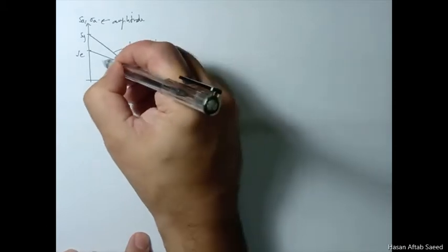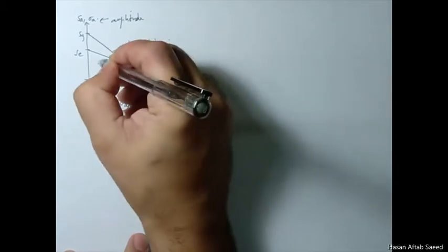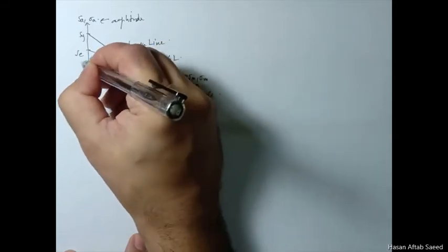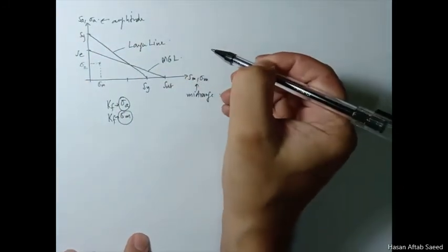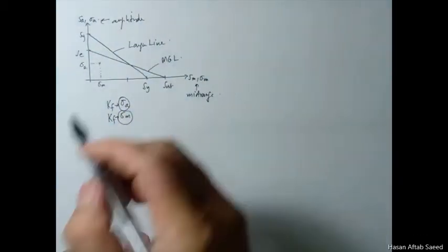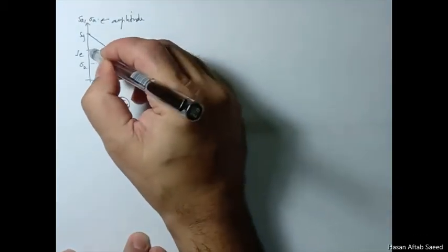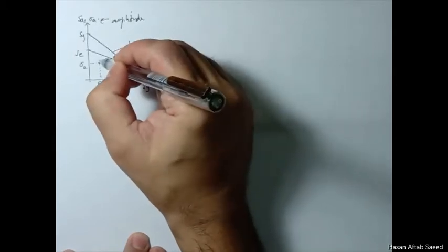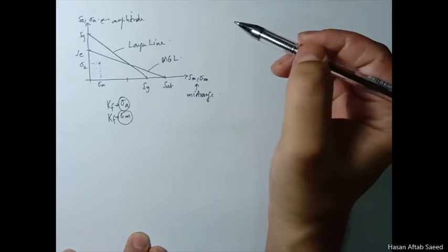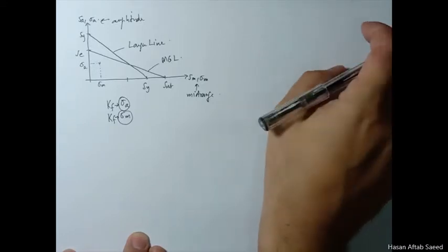And for example, if your point plots here, that is, this is your sigma m, this is your sigma a, then graphically you know that it is falling under both the lines, so it is safe as far as yielding as well as fatigue is concerned. So we should expect infinite life for this component.